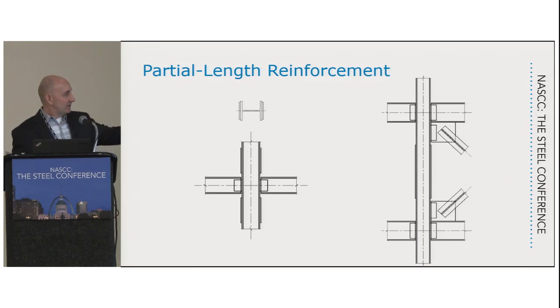And the reason is because it's kind of braced all in this section, and you're really only unbraced from here to here. So what difference is that going to make? And also, it's at the end of a column. The main part that's going to contribute to the strength of that column is at the center of the column, at the mid-height, I should say.